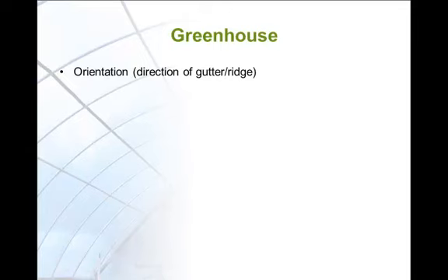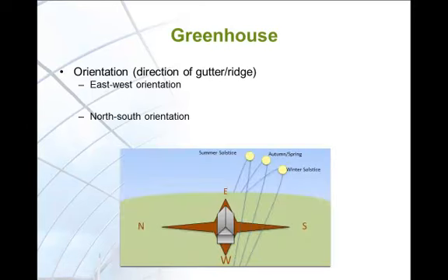Most conventional greenhouses are elongated shapes to minimize construction of labor-accessible pathways. Therefore, the orientation can be categorized into either east-west or north-south. As you can see from the diagram, east-west oriented greenhouses have more solar receptive surface during wintertime when solar angle is low.